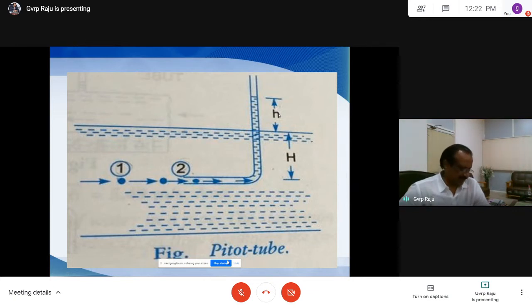The principle involved is that the velocity of the flow at a particular point is reduced to 0, known as the stagnation point. By measuring the pressure energy at this point, the velocity of the flow is obtained. Because of the reduction in velocity, there is a pressure change, and measuring the pressure energy enables us to find the velocity.